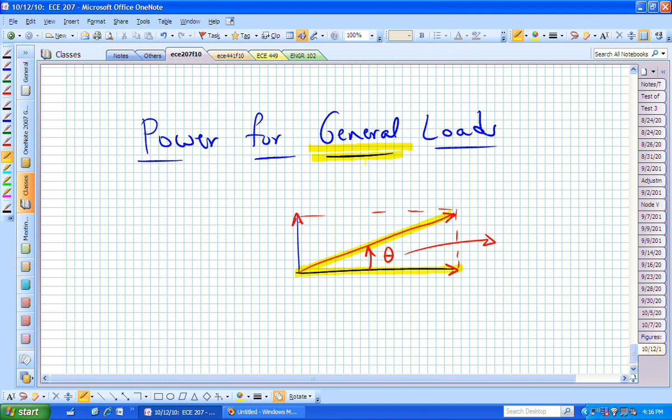You may know that you are going to have a power factor of 0.7. Well, now you throw a bunch of capacitors on that, you put in your capacitor bank and bring that angle down, and now you have less reactive part, so your complex vector is closer in length to your real or average power vector length.